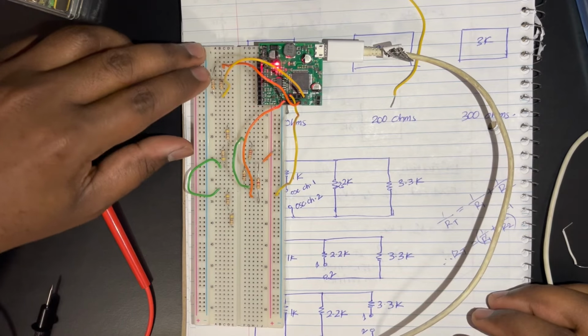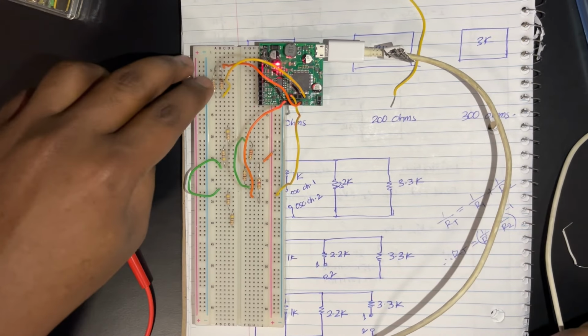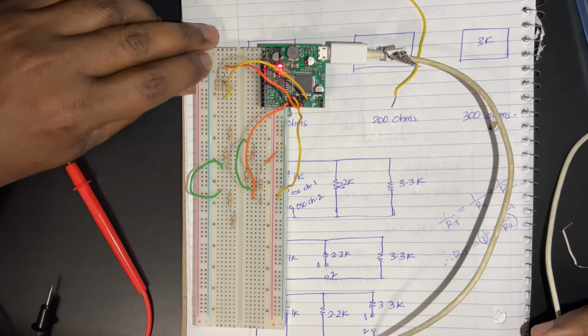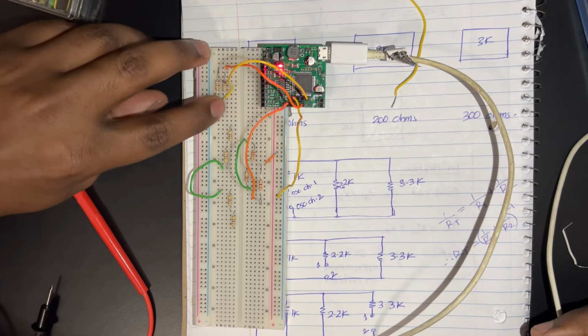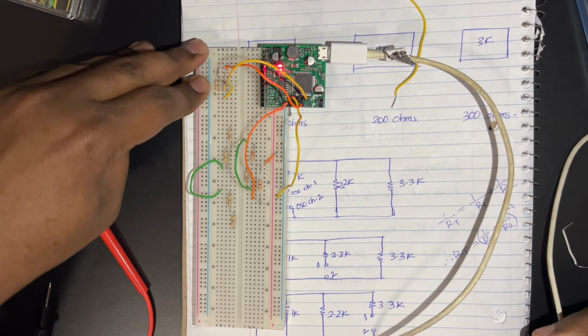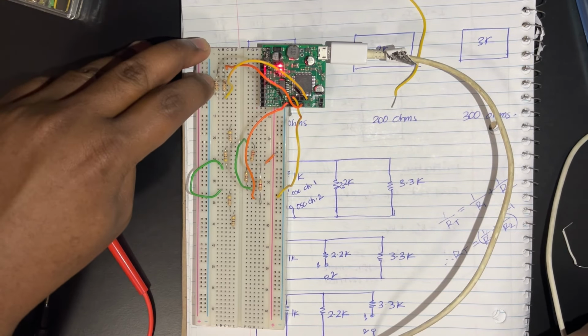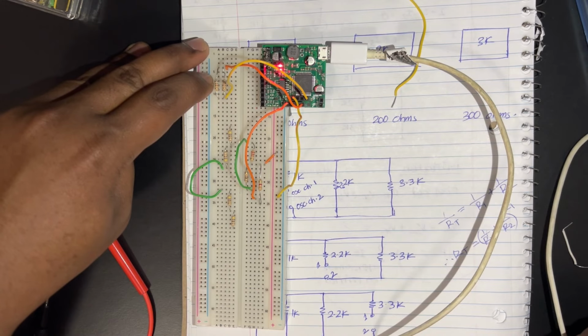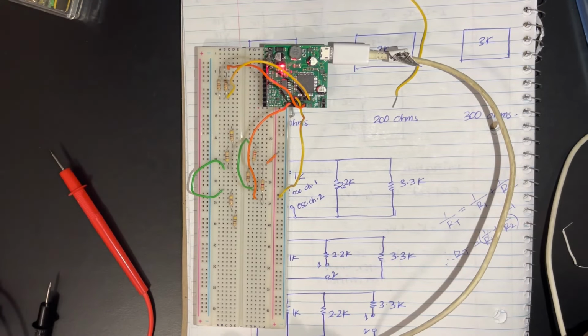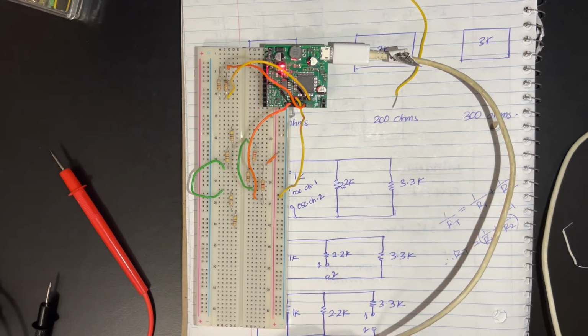If you were not able to see, this was the parallel combination that I talked about. I'm sorry about that. So oscilloscope channel 1 once again came over here, oscilloscope channel 2 over here, two 670 ohm resistors connected in parallel to make the value half, which is 335 ohms, and this is the value of the series resistance I'm going to be using to measure the current which is passing across 3.3 kilo ohms.